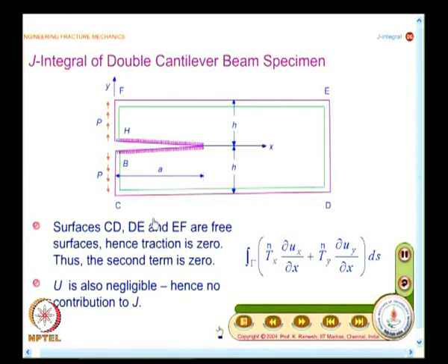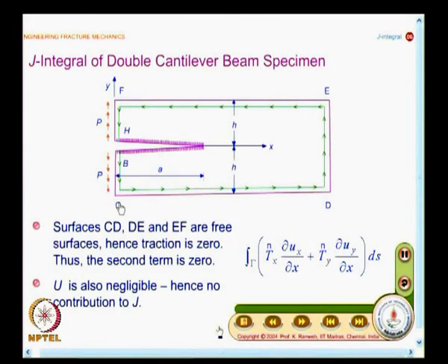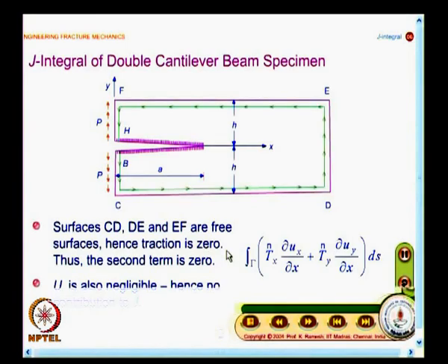And you have learnt in solid mechanics many things. Whenever we have a solid mechanics problem, if there is bending as well as shear, we would recognize the energy due to bending better than the energy due to shear. We will always neglect any shear effects in slender beams. We will also do the same approximation here. When we look at the surfaces FH and BC, you have only shear. So, whatever strain energy is introduced because of shear, we would neglect it.